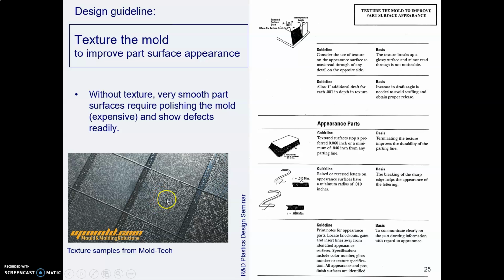So there's a mold pattern, and then there's like an electric eye that follows the mold pattern and etches the surface of the mold cavity to match the pattern, and you wind up with a mold cavity textured like, could be like leather or naugahyde or wood grain or sand or any of those.